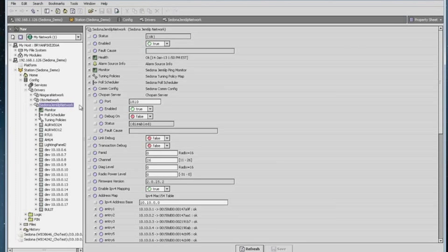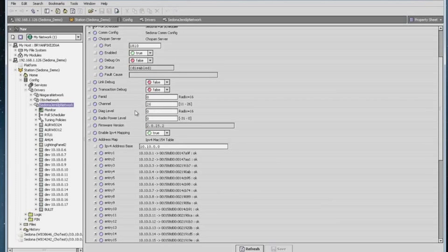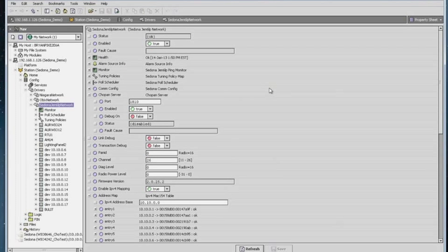All right, so back to the Sedona network as a brief recap. We've dealt with how to set up your Sedona network, how to utilize the address map for your wireless troubleshooting, setting up your PAN ID and your channel, enabling show PAN for your service PIN, and then enabling your network.